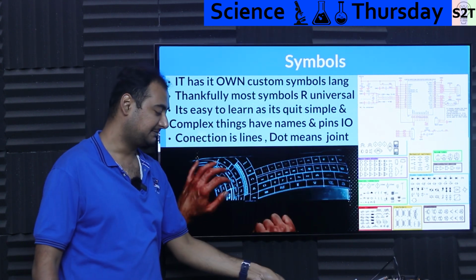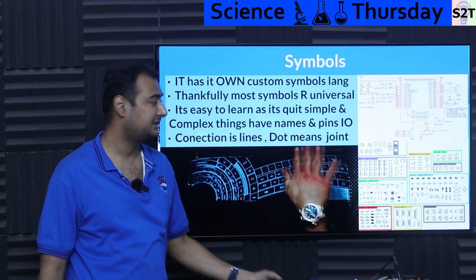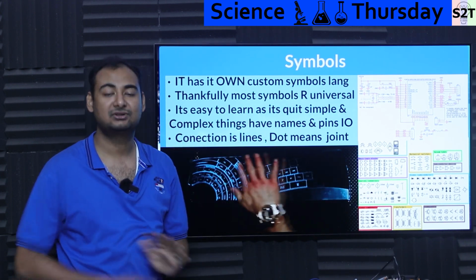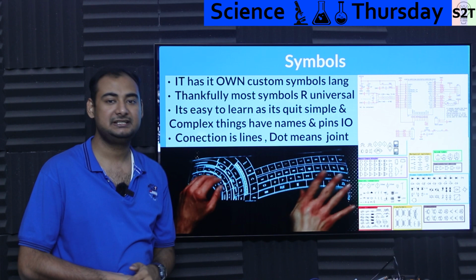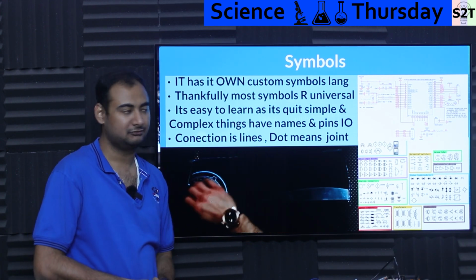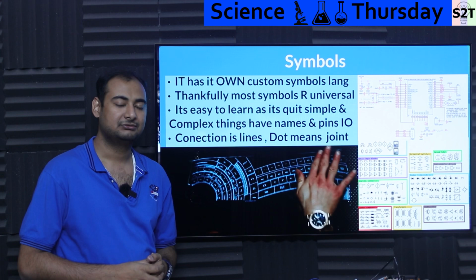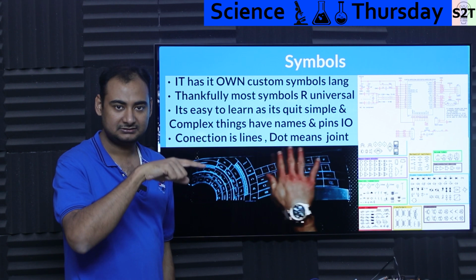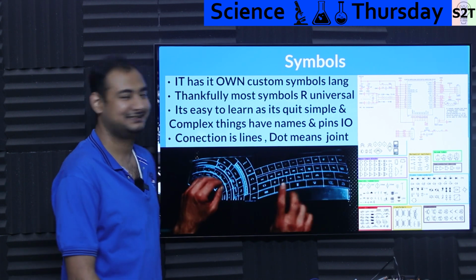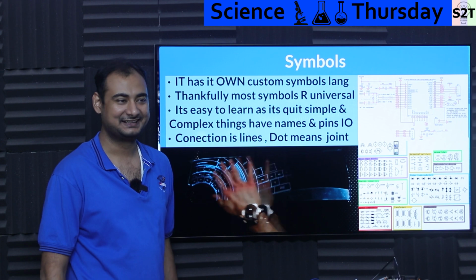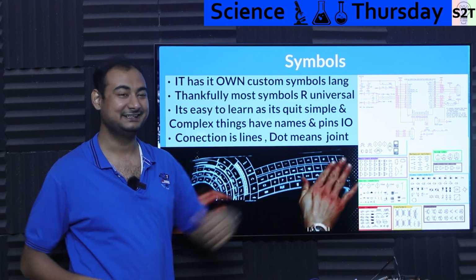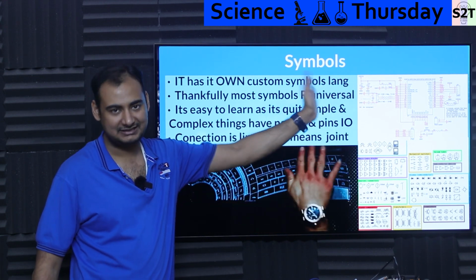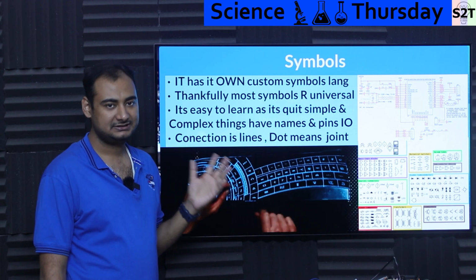So, for example, an ESP32 module. How would that module be drawn in schematics? It's just a box that has the name saying this is a module, and it will have pin counts. Nothing more than that. It's a very easy way to convey complexity. Nobody's going to draw a full CPU processor. All they're going to draw is a square with as many pins as needed. I really want to look into those people's files: 4,000 pins, figure it out in a motherboard. Damn. Same rule applies: you just have a box that has pins coming out of it. It's quite easy to learn.